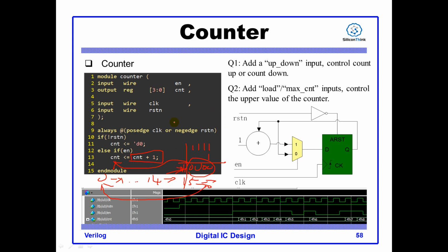And the second point is something new for you. We have declared the direction and the signal type along with the signal name in the round brackets. We have merged them in one place. This is also allowed in Verilog. You can merge them in one place.